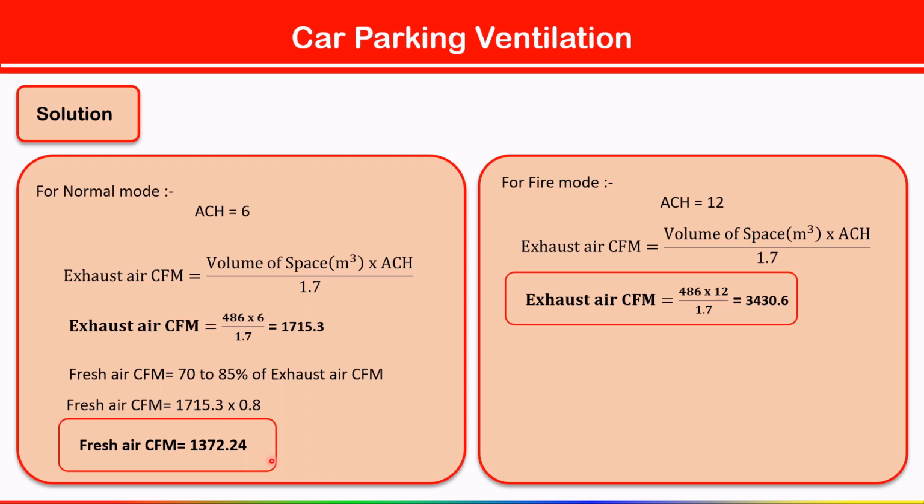And remember one point, everyone: while doing the duct size, always, because duct size totally depends on it. If you are doing the exhaust air duct size, we have to take that exhaust air CFM, the Q value, which is that much. So duct size always depends on fire mode.